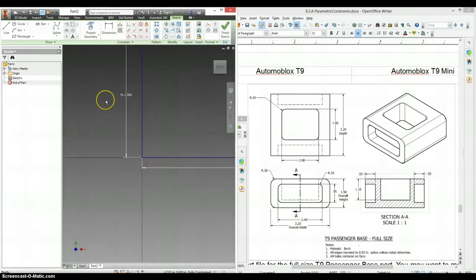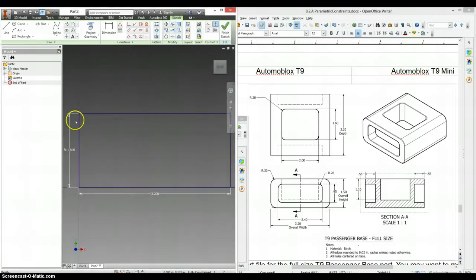Okay, so what that looks like on paper is if we draw out a rectangle, I make this dimension first, so this is my D0, then this is going to be D0 times 1.5, which is what we wanted it to be, over 3.5. Perfect. Okay, the fillets on the edges here, it says this is part of the equipment that they're using to make it, so we can make these as exact numbers. This is 0.3, and that's for all of our edges.